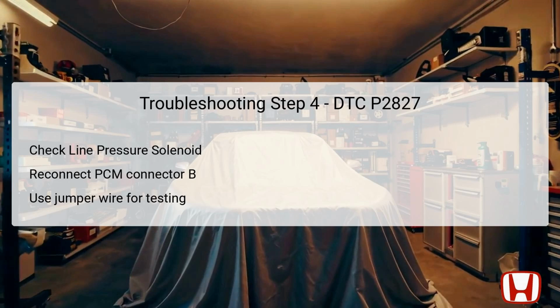With this setup, turn the vehicle to the on mode again and clear any previous DTCs using the HDS. It's essential to raise the vehicle securely and allow the wheels to rotate freely while testing the accelerator position. Monitor the APP, accelerator position sensor readings on the HDS, checking them for any abnormal variations.